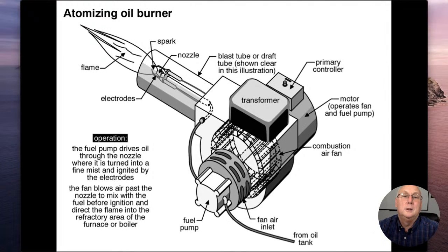Oil burners, I don't know what to say about these things. Everything is kind of confined. So unlike natural gas, which comes into our house under pressure, and even though we lower it to 1/4 of 1 psi, same thing with propane, it comes into the house under pressure. Oil does not. Oil is in a tank, and it's just going to be gravity and a liquid that comes through it. And then it'll create a siphon to pull more oil into it.